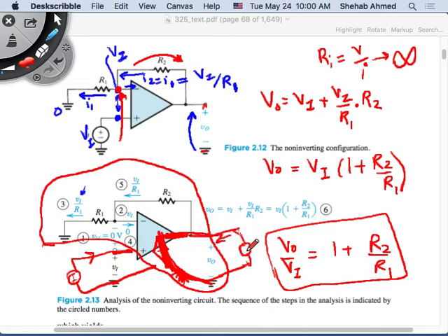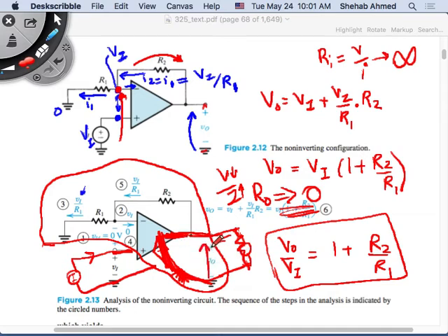This large current, take a small voltage divided by a large current. It will be what? Small voltage divided by large current. So what is our output? Ideally 0. So this is a nice device. It's a device that has infinite input impedance, 0 output impedance. So there's no effect on the loading that will change the voltage of the output. If I put whatever resistance here, a small resistor, large resistor, I will still not see a change in the output voltage, which is nice.